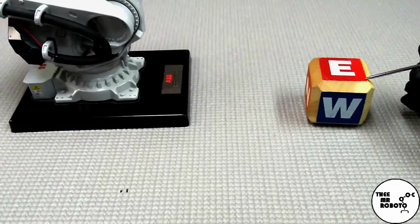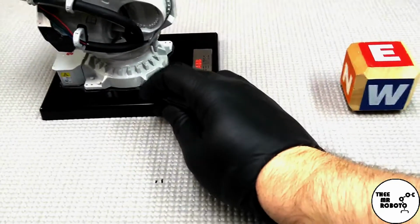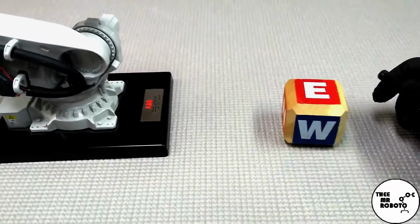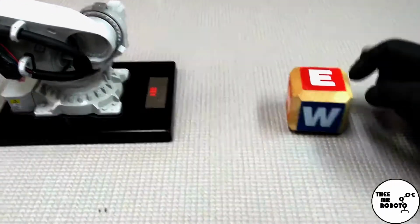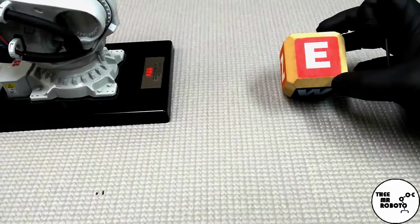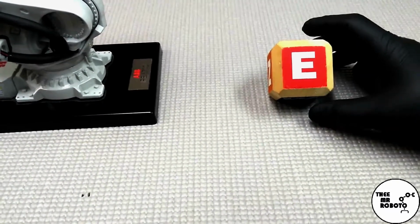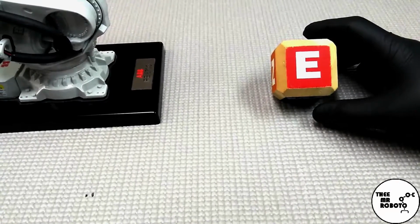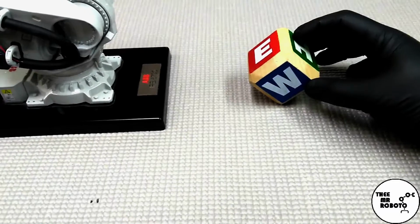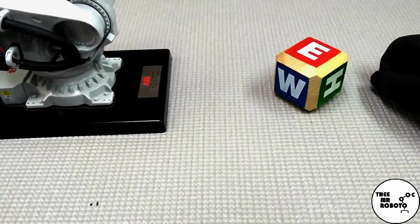And then you would have a Z offset, which would be your dimension from the height of this table down to this surface. So those would be your 3 main numbers. Then, if it was at an angle, you would see a rotation around, in this case, the X. If it were like this, it would be a rotation around the Y. If it was like this, it would be a rotation around the Z.